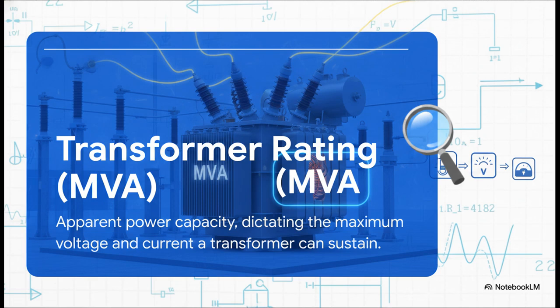The size of a transformer is given by its MVA rating. That stands for megavolt amperes. It's what we call apparent power. You can kind of think of it like the total size of a water pipe. It's not just about the pressure, which you can think of as voltage, or the flow rate, which is like current. It's the combination of both. It tells you the absolute maximum electrical load that transformer can possibly handle.